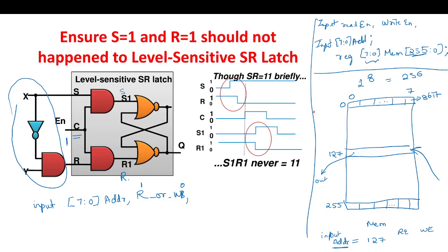And if it is writing, so data also should come from the user. And output, if it is a reading value, then the output should be the read data. And how many bits will this data be? It will be again 8-bit, or how much bit width you have given here, that much, and output will also be 8-bit because we are defining it.